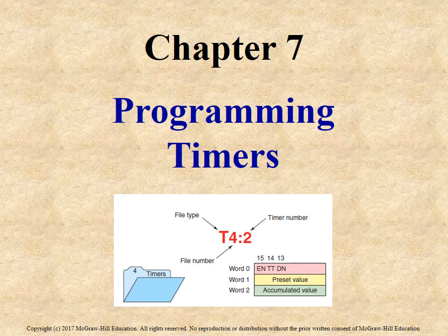Though the word and bit allocations are still fairly close to the same. As you can see here, they have a control word, a preset word, and an accumulated word. We have the same thing set up in the 5000 world, only it's a 32-bit word, and of those 32 bits, there's again 3 bits used for the control word. That's the done bit, the timer timing bit, and the enable bit.